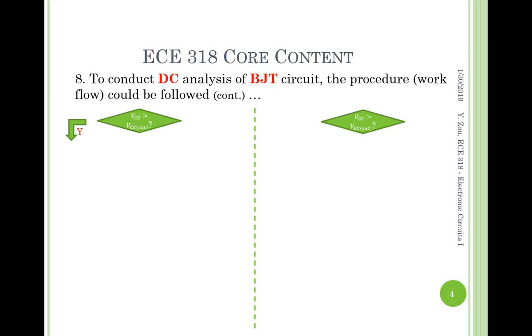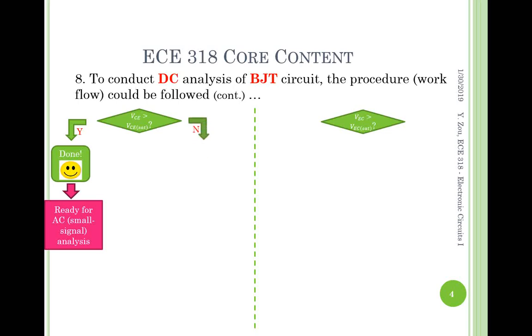if VCE is greater than the VCE saturation voltage, that means our original assumption of active region was correct. And if so, we're done, in the sense that the IC we got is ready for our later small signal analysis. But if VCE is not greater than the VCE saturation voltage, that means it is not in the active region.